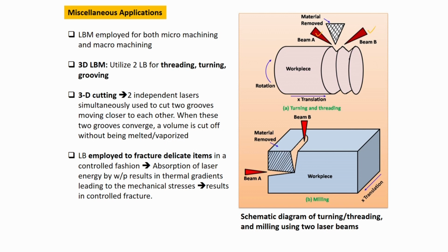Laser beam can also be employed to fracture delicate items in a controlled fashion. Absorption of the laser energy by the workpiece results in thermal gradients leading to mechanical stress, which results in a controlled fracture.